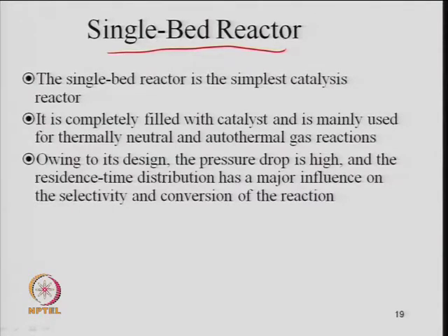So, the selection especially depends on the deactivation performance of the catalyst, the conversion level which is desired, and the endothermicity or exothermicity of the reaction. So, that will depend on the heat transfer, right? That will decide the reactor design, how the heat can be removed from the process, or whether it can be adiabatic, isothermal, or non-isothermal type of reactors. So, different names or different design approaches have been given depending upon the heat transfer, mass transfer, and so mass balance, energy balance, and momentum balance for pressure drop calculation. So, all these things should be checked for the commercial reactor design.